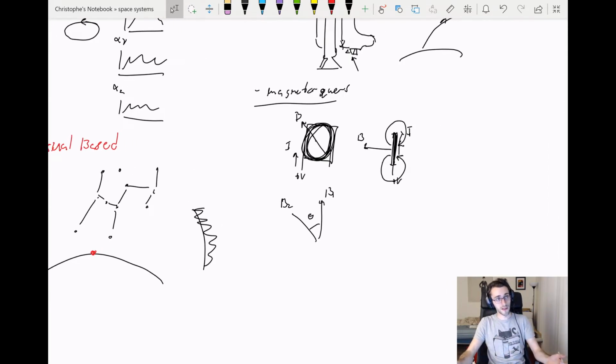The advantage of this is, if your orbit is stable, and you're going through that orbit day after day, you will begin to align yourself with the direction of that field. Especially if you are tumbling, or say you've been dispensed from whatever dispenser you're shoving a CubeSat out of, and you're tumbling through space with really erratic, chaotic attitude shifts, where other active control systems like thrusters have to figure out where am I pointing, where do I have to actuate these thrusters really quickly? They just can't keep up with that.